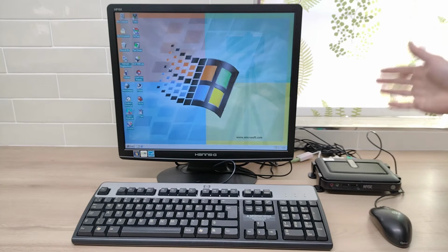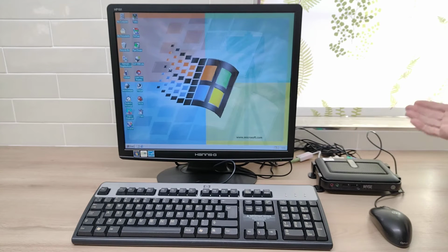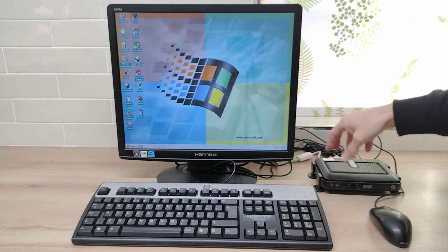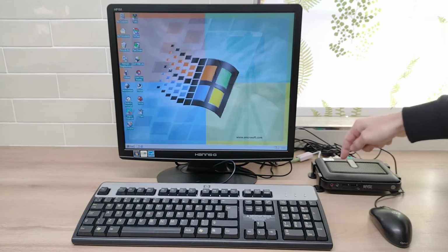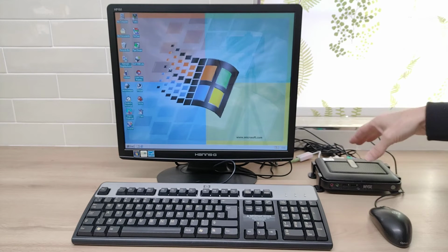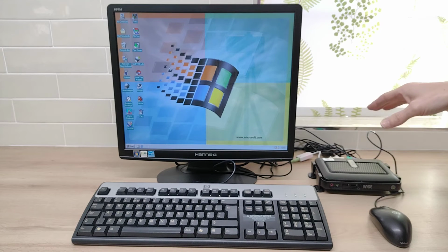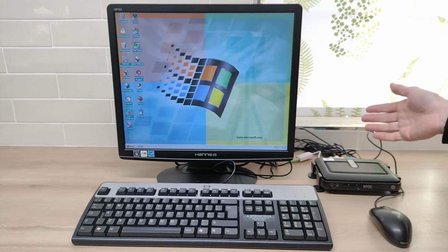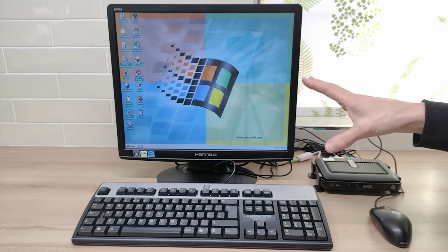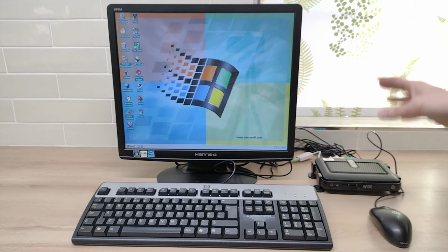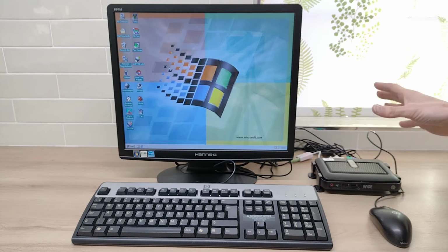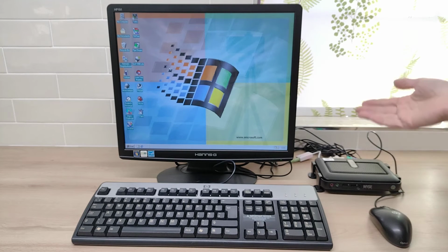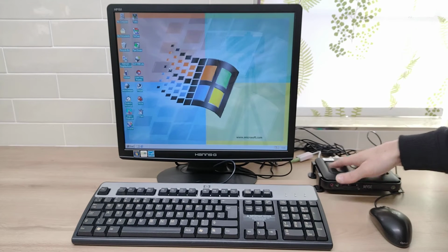Now the reason that I don't think they're installing, and this is only my best guess at this time, is as we saw earlier in the video when the top was off, there's only one IDE port on here. I found some forum posts from somebody having the same problems on a different system, and that too only had one IDE port, and their drivers were crashing and failing to install in the exact same way that they were crashing and failing to install on here.